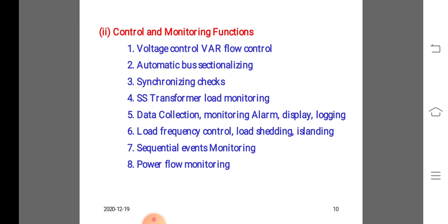the most common. In digital telemetry, the quantity being measured is converted to a code in which the sequence of pulses transmitted indicates the quantity. One of the advantages of digital telemetry is the fact that accuracy of data is not lost in transmitting the data from one location to another. Digital telemetry requires analog to digital, that means A to D, and possibly digital to analog, called D to A converters.